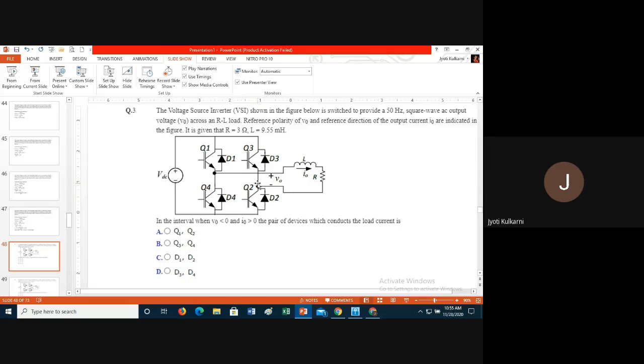Q2 positive. Now Q2 positive, I want to connect to the positive plate of the supply here. It means obviously I have to move in the upward direction. If I want to move in the upward direction, which device do I prefer, IGBT or diode? Because through the IGBT, if I want to go, I have to go in the opposite direction to this arrow. So this arrow won't allow me to flow in the opposite direction.